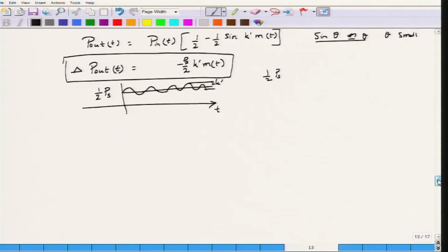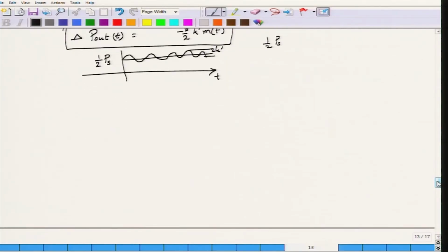Having seen this intensity modulation, let us move on to a different application of MZM. Okay. In optical communication systems, we transmit information. When we modulate the information onto the light signals, we also want the light signal to be pulsed. So, we send out optical pulses carrying information. These optical pulses can carry information both in their amplitude, phase, or in general quadrature amplitude modulation. However, optical pulse shaping simply implies that I am able to generate optical pulses and then modulate these optical pulses using any of the modulators that we have discussed.